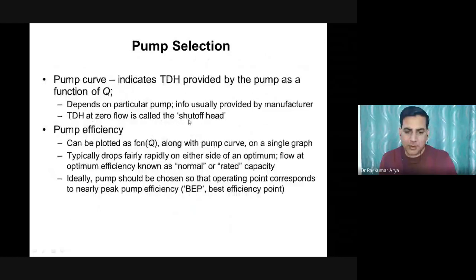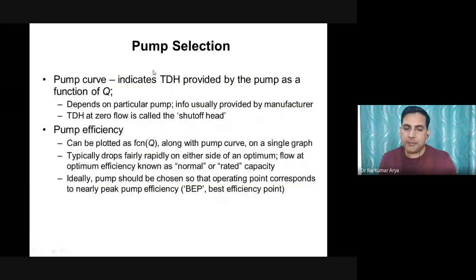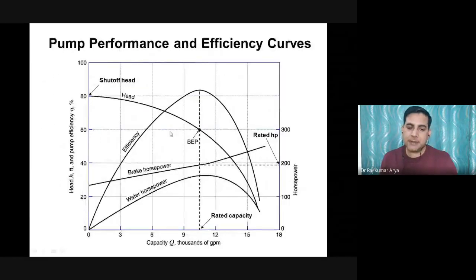Now before that, this is what I told you here, the efficiency of the pump. This is the discharge capacity and head of the pump. Each pump has some power, and power is calculated as P equals Q H rho g, where H is the head of the pump. So the plot is plotted in that way. The capacity is how much you want to withdraw. Based on that, you have an available head, how much head would be delivered. You are multiplying by the efficiency also here.